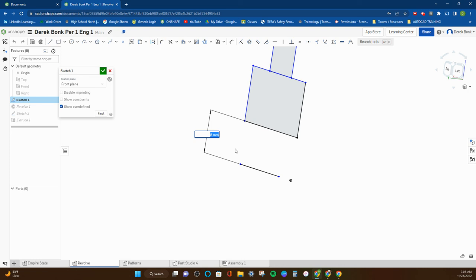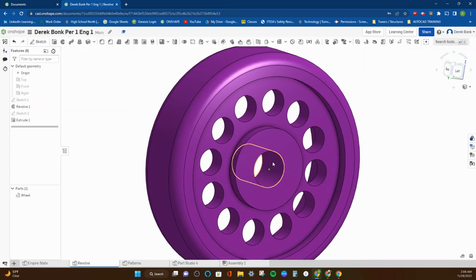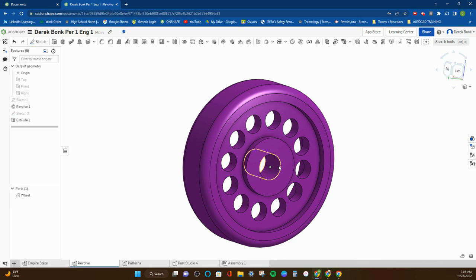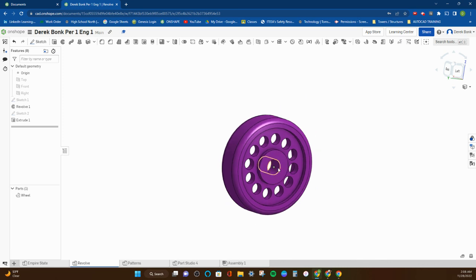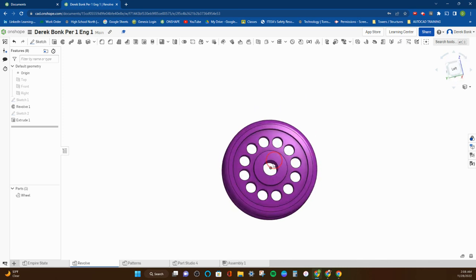So I would end up making this like 8.15 would be my actual measurement, and at 16, so it'd be 16.3 millimeters across now mathematically, and I'd be able to take a 16mm steel rod and fit it, and I'd be able to 3D print something like this without much trouble at all.